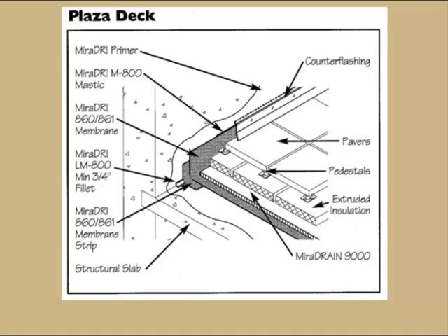An example of some of the considerations when you're looking at below-grade waterproofing, as a plaza deck really can be considered similar to a roof. You have occupied space below this area that has a high potential for standing water. So any place we have a horizontal to vertical transition needs to have multiple layers of protection. You can see at the corner point there's a fillet type joint system in there, and then there's a wider flashing that extends up and horizontally, and then finally the large area waterproofing comes up to it and extends vertically up to a counter flashing.